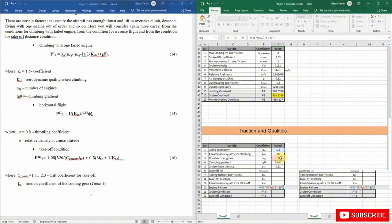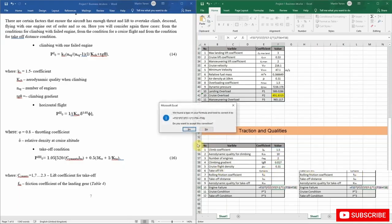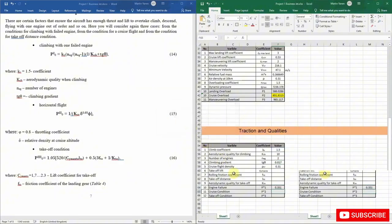So this is going to be multiplied by 1 divided by the climbing quality, which is equal to 10, plus the climbing gradient, which is 0.017. Let's close a bracket here. I needed to close one more bracket, but Excel will close it instead of me. So let's select OK here. And here you can see that for the engine failure, you get the traction coefficient equal to 0.351.